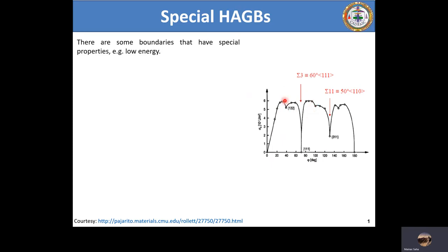Now the second interesting thing that we can see from this plot, and I had also asked this in the previous session, so today I'll be answering that in brief, is that when we compare this part of the grain boundary energy versus misorientation plot with this part, we see that these two parts are nearly symmetrical with respect to each other. This comes because of the 3-fold axis of rotation in a cubic material. For example, the plot that I'm showing here belongs to aluminum.